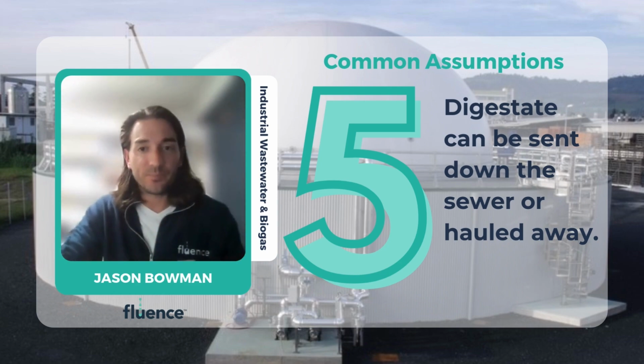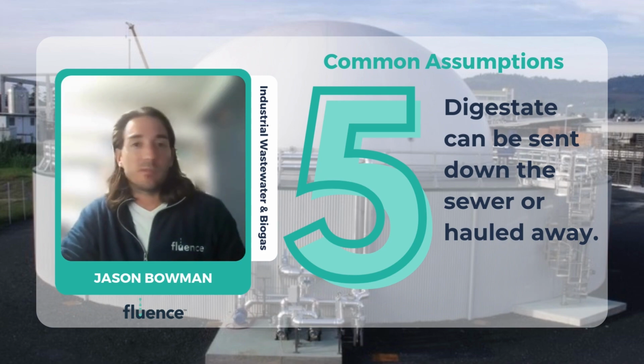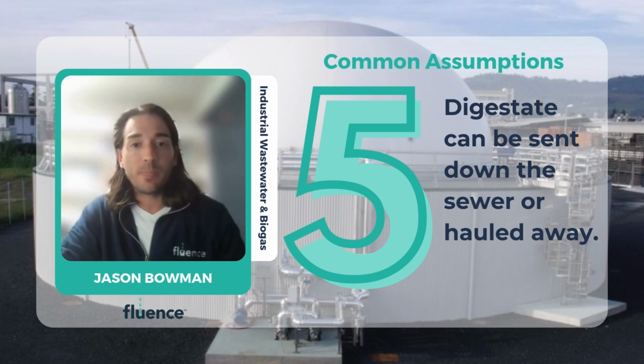a small city. So let's try to put this into another perspective, and that perspective is that you're going to choose to haul all of this liquid digestate off-site. So at 60,000 gallons a day, your average tanker is going to carry about 6,000 gallons if you're lucky. Most tankers are going to cost you $1,000 per haul. So that's 10 trucks a day, that's $10,000 a day. That adds up to almost $4 million on an annual basis.